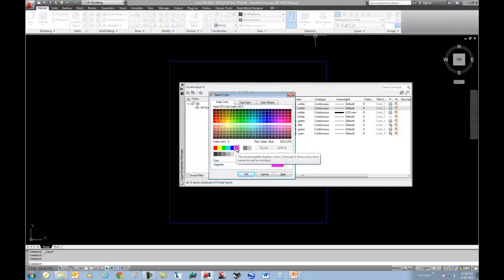color. And you'll remember that I mentioned that many times, an industry standard is that a civil firm will use colors to determine line weight. So, for example, what's often practiced is color number 1, which is red, that might be a thin line weight, and then color 2, which is yellow, a little bit thicker, and then green, thicker. It continues to get thicker all throughout these standard colors. Then they may reserve these bottom colors for grayscale, so instead of printing black ink, it would print shades of gray.